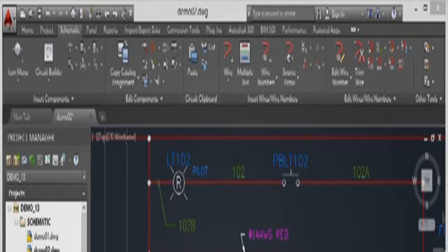So what you do is you select your component here, right click, attributes, and you want to move the attributes like so. So select the attribute to move. So I'm going to select both actually in this particular case first, and then press Enter to confirm. And I'm just going to move them so that they're a little bit further away like that, and then Enter to finish.